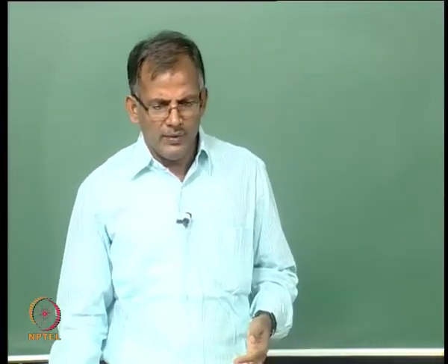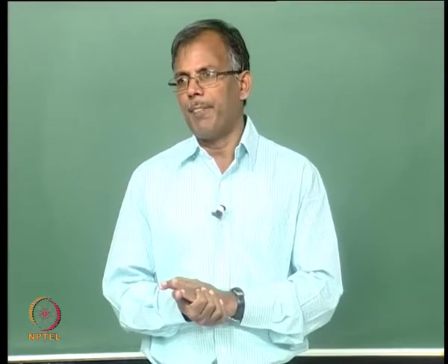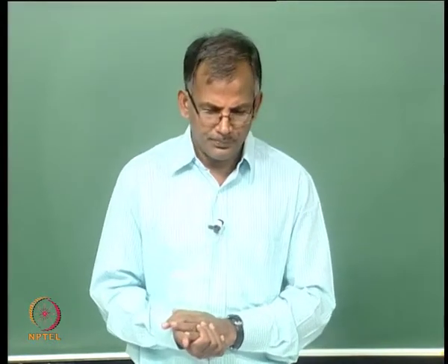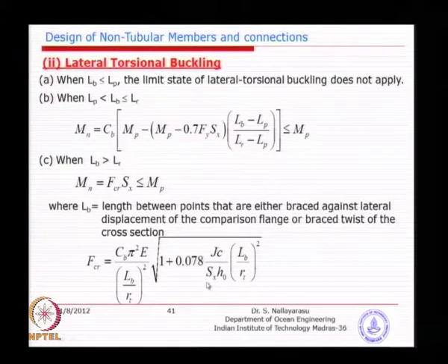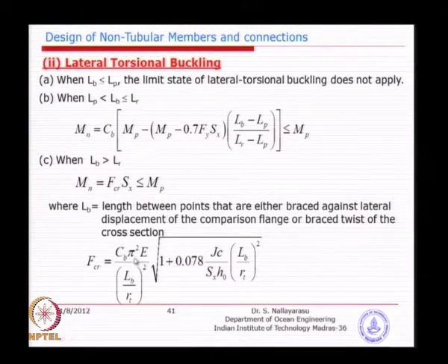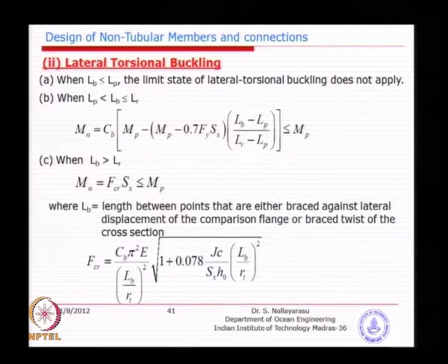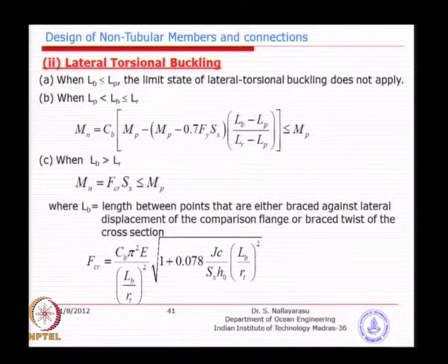So you can see here, allowing torsional buckling to happen is not a good idea, it is just going to reduce the capacity. And again you will see large formulas, but the form of the formula is very similar to Euler buckling. You can see here only an additional term is added on the right hand side, which is empirical, just to fit the test results. So FCR is calculated using pi squared E, and here you see a slightly different form of LB, because it is not anymore a KL by r, it is basically the torsion prevention by means of lateral compression restriction.